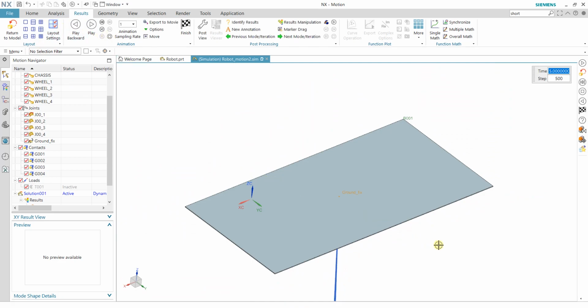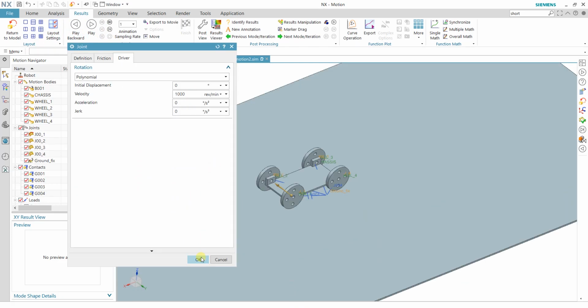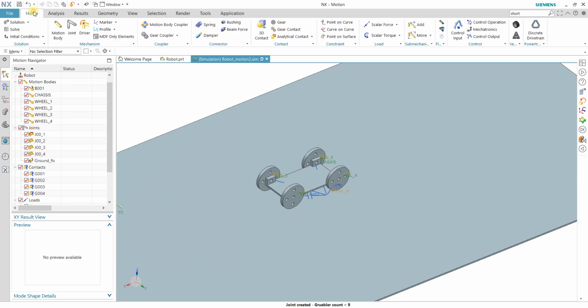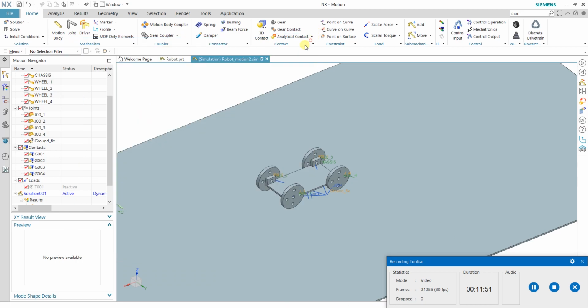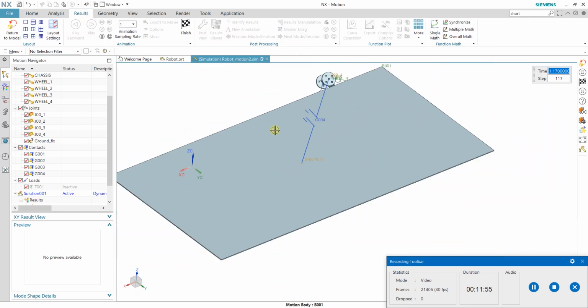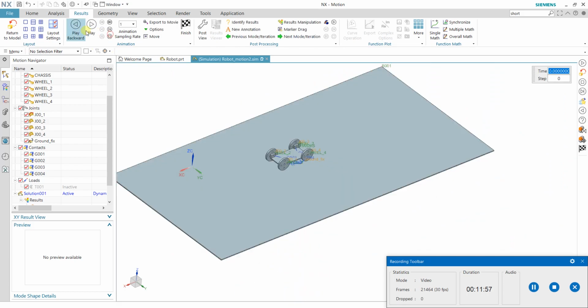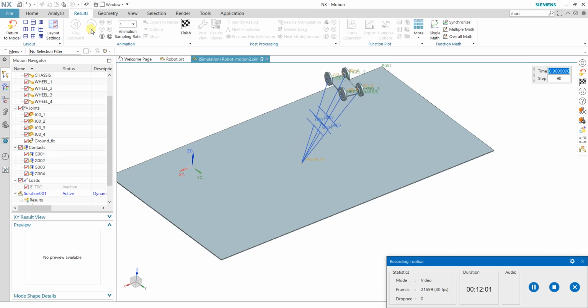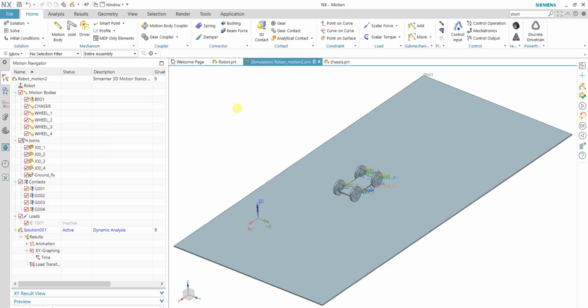So in this case, if something is locking your movement, the simulation is going to fail. So be careful with this type of driving the joint. Now by increasing it, you will see the same action as we had with increasing the torque, because now we have enough speed to actually turn the car around.